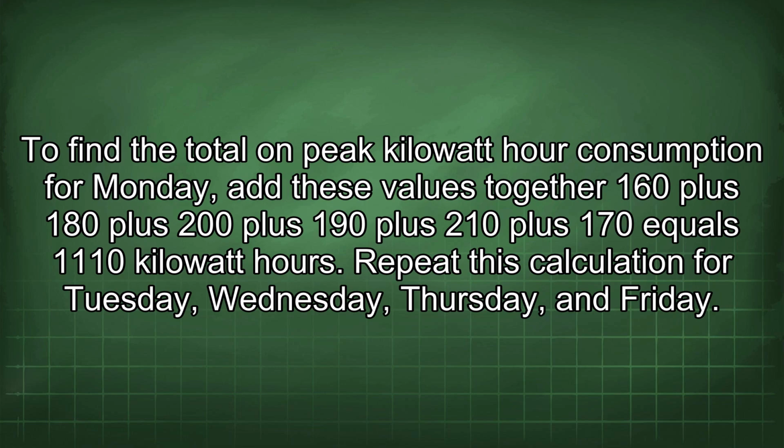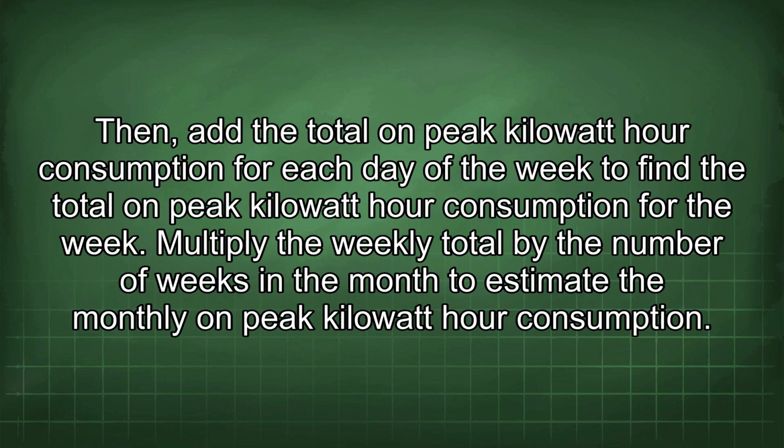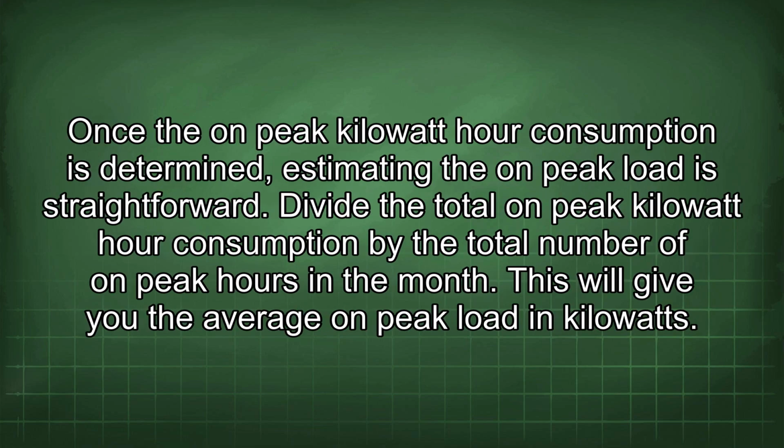Repeat this calculation for Tuesday, Wednesday, Thursday, and Friday. Then add the total on-peak kilowatt-hour consumption for each day of the week to find the total on-peak kilowatt-hour consumption for the week. Multiply the weekly total by the number of weeks in a month to estimate the monthly on-peak kilowatt-hour consumption. Once the on-peak kilowatt-hour consumption is determined, estimating the on-peak load is straightforward.